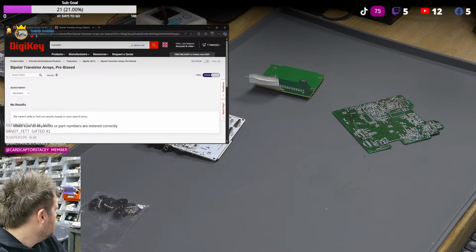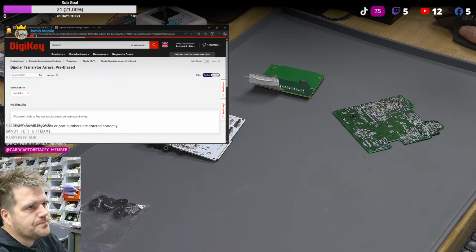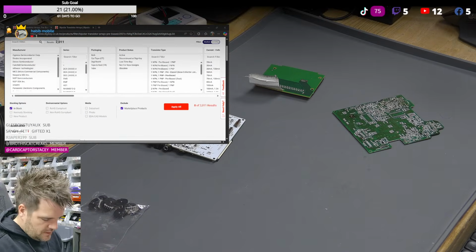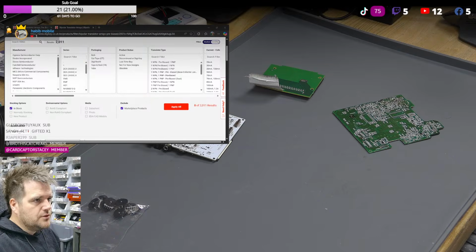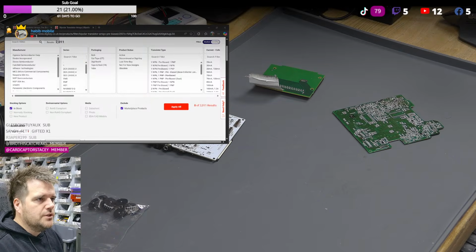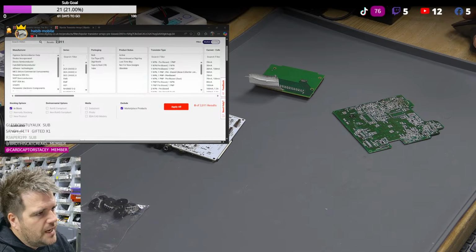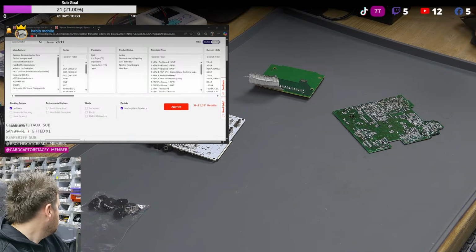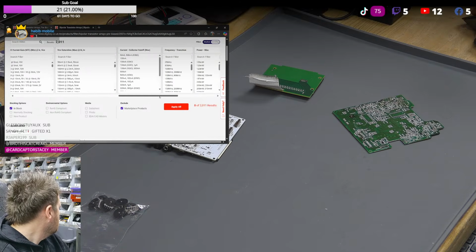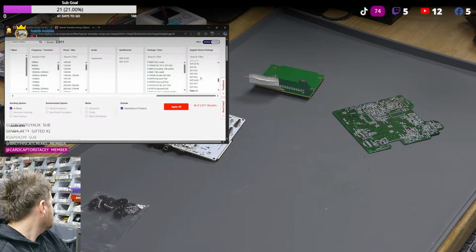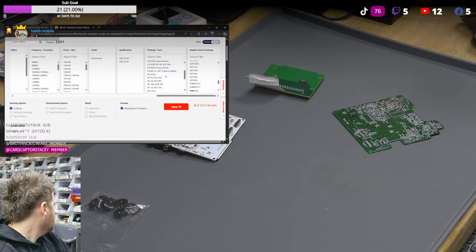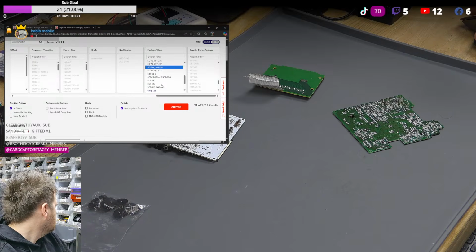So there's none in the SC74. So let me just pull up those SOT23-5 package alternative names. I can't remember what they are. There's the SC74, the SOT753 is another name for it. So let's try SOT7. Nope, can't see that. I wonder if we've got one in here. There we go, SC74A. Let's clear the other one, so use package case instead of that.